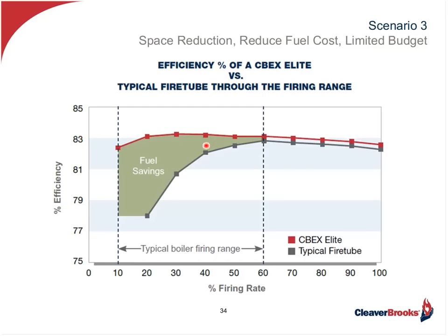And now added to that is the loss that is incurred because of cycling. Remember, every time that boiler cycles off, it goes through a post and a pre-purge. That's about 2 minutes of blowing ambient air through that unit and cooling it down. Now remember, those BTUs are derived from that burner because it's burning cash. Every time you start purging air through those BTUs that were going into the water, you're cooling it down. Those BTUs and that cash is going out the stack. You want to limit that cycling.